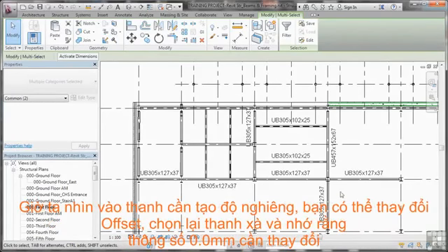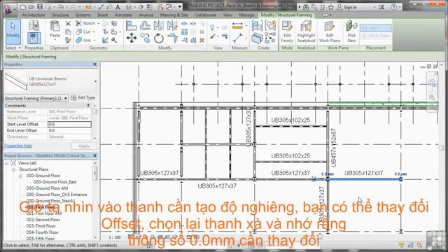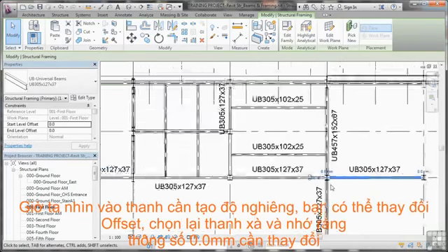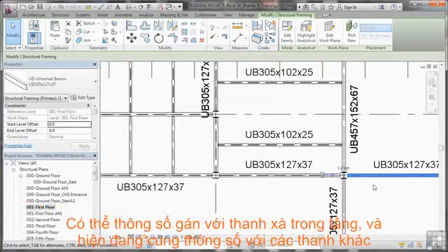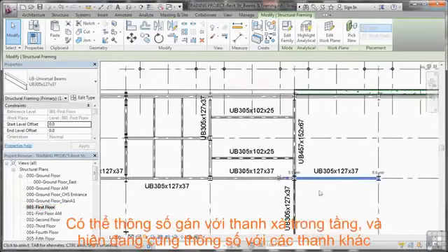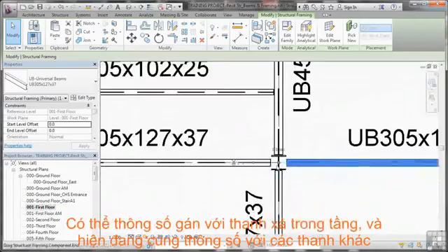You can slope your beams by changing the offset. So I'll select this beam again, this one here, like so. Now you'll notice there are some 0s in place. I can change the offsets here if I want to. Now they're all set at 0, so that's a level beam, and also the 0, when I drag the ends of the beam there, is at 0 as well.